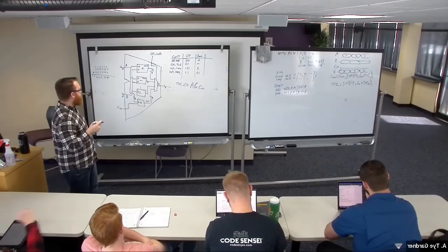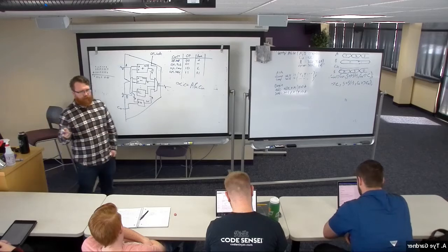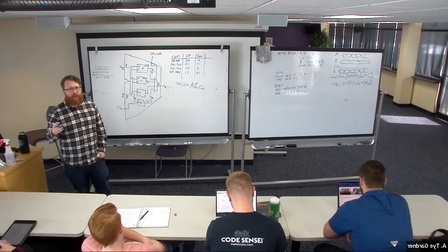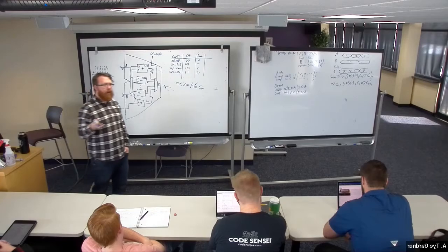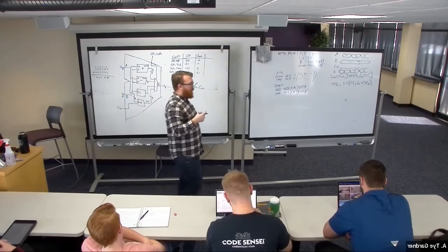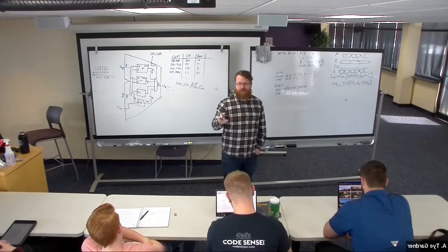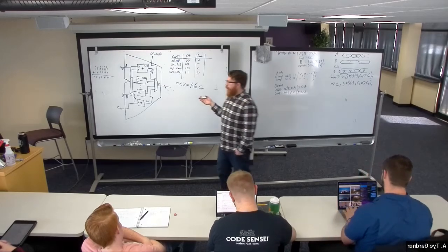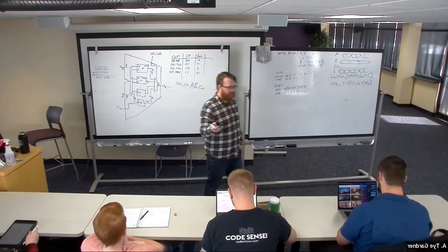The subtraction is going to be kind of an interesting one that I need to change the lab write-up for, because right now the current lab write-up doesn't have the subtractor in it. We want to be able to subtract numbers, but we're going to have an issue: if we want to subtract 2 numbers and be able to go negative, we need to store everything as 2's complement, right? Or sign one or the other. So I have to rewrite the project to make it clear how you're going to implement that part. That might be the trickiest part, other than just connecting them together.